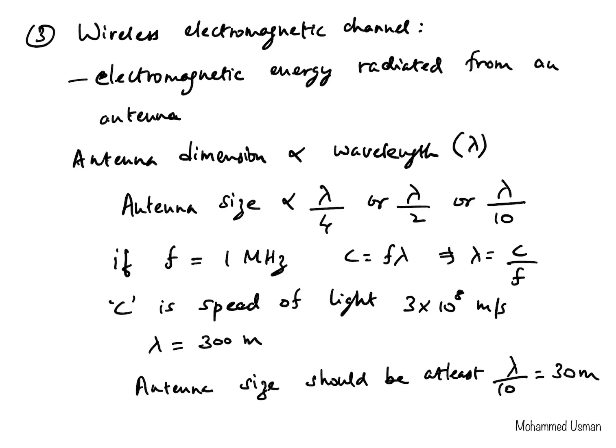Okay, so imagine having a 30-meter antenna on your mobile handset, right? The mobile handset is hardly 5 to 6 inches, and therefore a 1 megahertz signal is too difficult to be transmitted effectively from a small handset, because for effective radiation we are talking about the antenna size being about 30 meters.